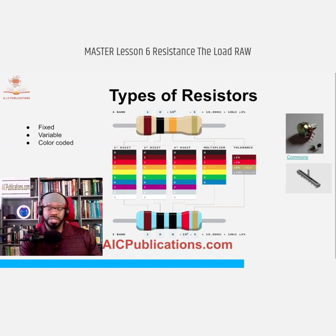Now, the resistor in the image that you're looking at has a value of 220 ohms with a tolerance of plus or minus 5%. This means that the resistor value would be measured within a window of 220 multiplied by 0.05, which gives you 11 ohms, so it would fall in the window of 220 minus 11 to 220 plus 11, meaning this resistor would be in the range of 209 ohms to 231 ohms.